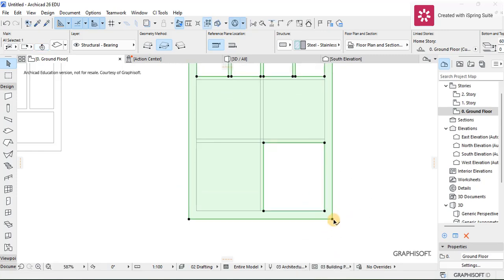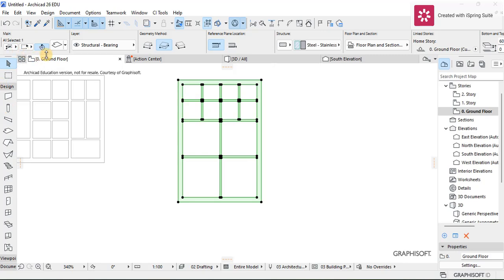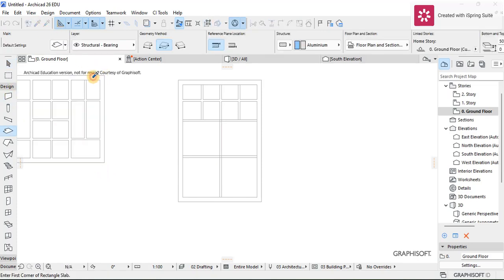These sections that I want to be bigger, I'm just going to show you in the design. Yeah, so then I'm going to take my slab again, and then I'm going to highlight these sections and make sure they are made of steel by taking attributes from the steel. So I'm going to select this and let's see if they're steel. Yeah, so just take attributes from the steel slab. Yeah, and then we inject it on these ones.